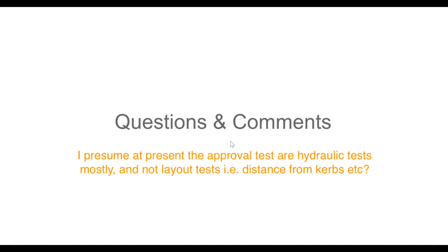But in the approval settings, we have actually made some parameters that could be tested, such as node losses, that's manhole head loss, the size of the pipe, the link size, the coordinates, whether you have clash in your conflict, and the minimum cover depths that need to be specified.